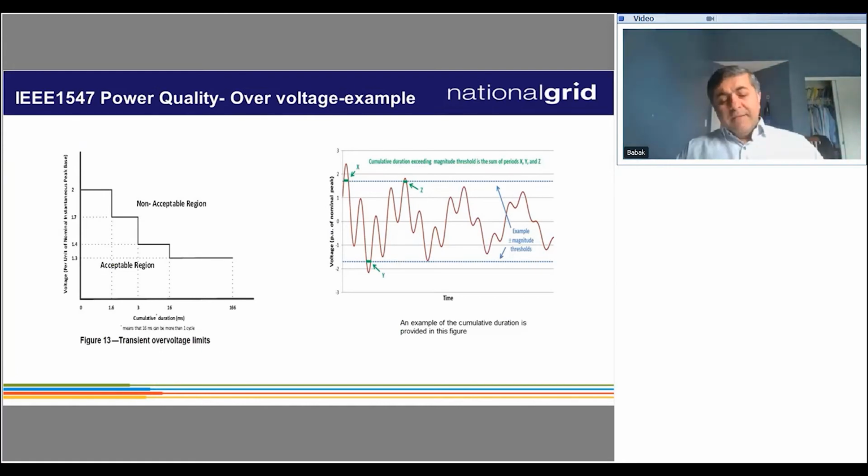One of the challenges that we're starting to see in the industry in terms of voltage issues is not only steady state overvoltage, but also transient overvoltage as well. Because the penetration of DER is growing, it's time to pay attention to even sub-cycle overvoltages. And so what we did, this is all new, it did not exist in the old standard.